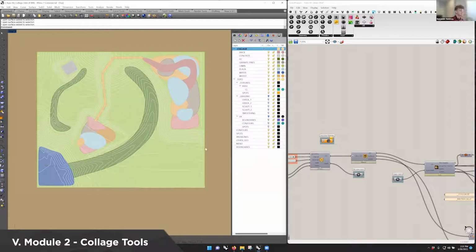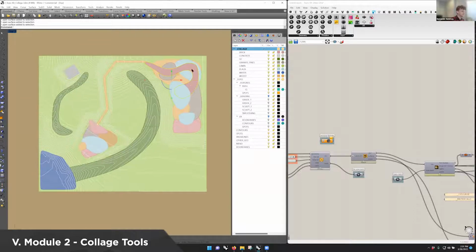If I go into the top view and look, you'll see a picture of what is going to happen once you start running the collage tool. You'll see that the red zone, even though it's a larger piece, because this blue zone is above it, you can't see the section below the blue zone. It's cutting it away. That is really how the collage tool works.